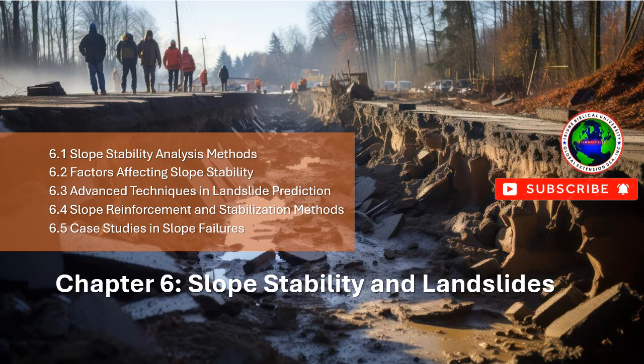Discretization. The slope is divided into a grid of points, and the equations of motion are solved for each point using finite differences. Dynamic analysis. FDM is particularly useful for time-dependent analyses, such as assessing the impact of earthquakes or rapid rainfall infiltration on slope stability.